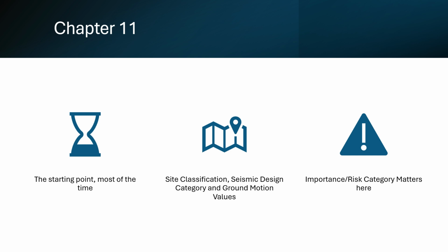And there are restrictions for seismic design categories, with F being the most restrictive. You have restrictions on building height, and certain building systems you're not allowed to use for more in-depth seismic design categories. So it's important to determine that up front because you are limited in what you can do if you are building in a seismic heavy area, or your problem statement is focused on seismic heavy criteria. So that's very important to determine at the beginning.